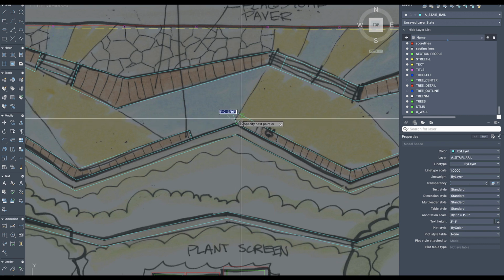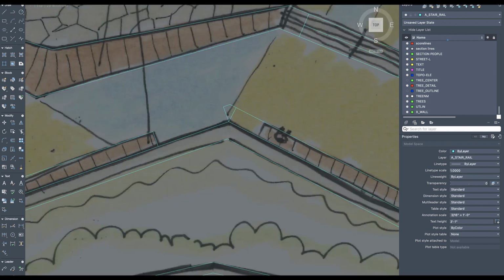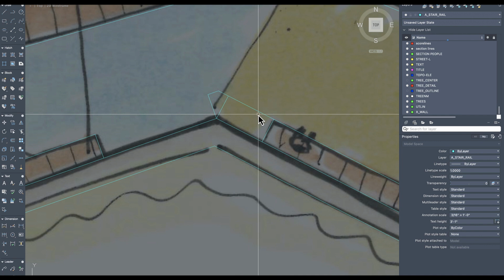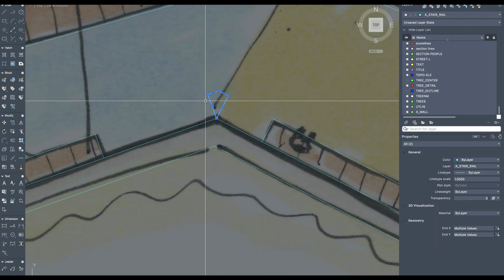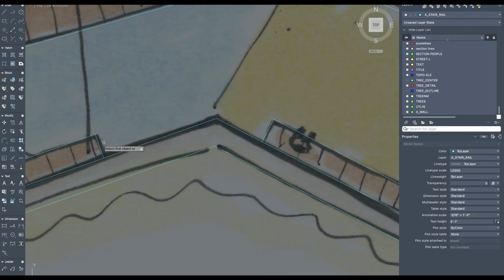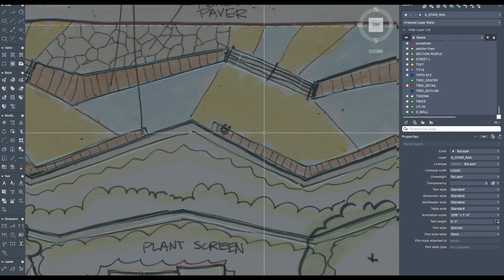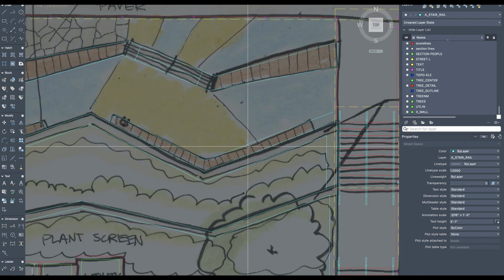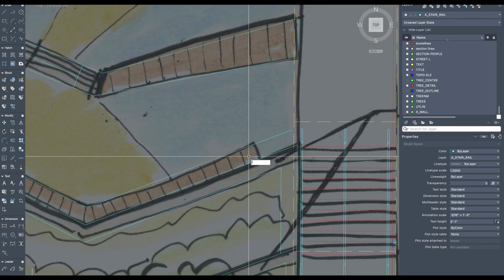Same idea here to here. Do a quick distance, 3 feet offset. Just typing in 36, so I don't have to type in the foot. Trim that. Don't need this line work. We're saving our last radius in there, that 12-inch radius. Just going to round these off. Might be a nice little detail for the bench right there, even having it in this curve. And one last measurement to kind of get this thing in order.